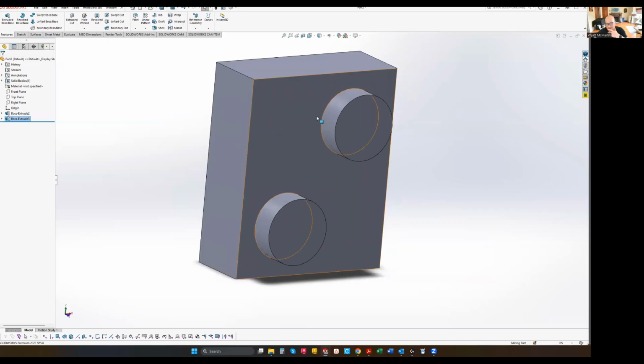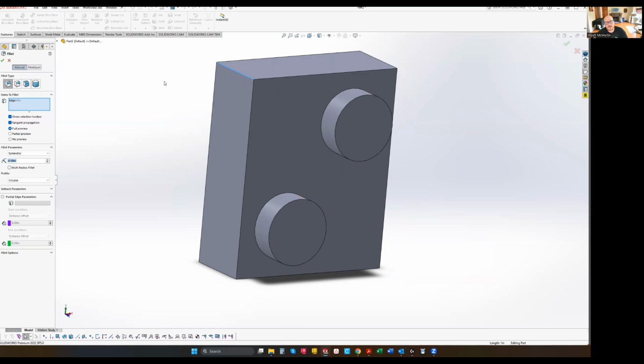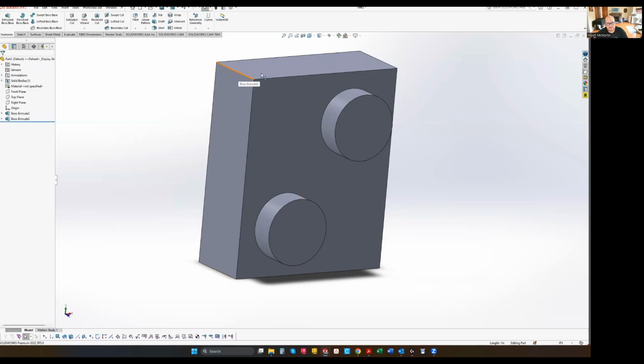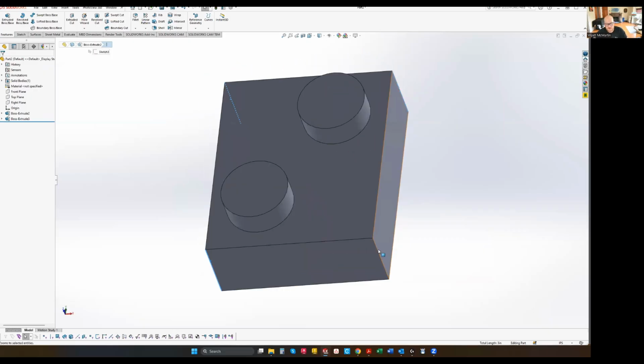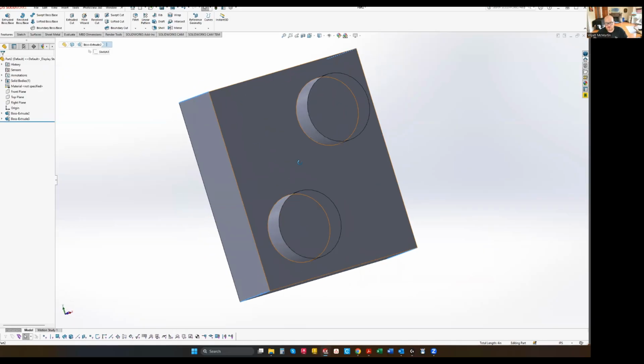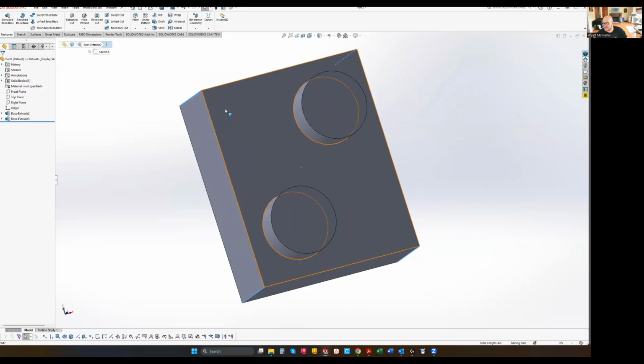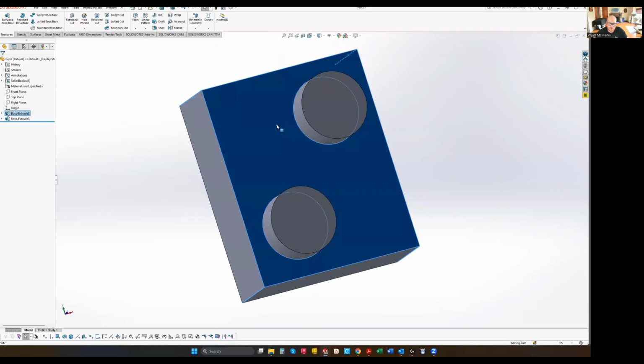So first thing, you can create these fillets one at a time. I think it's definitely better drafting practice, and it also is just nicer for somebody else who might come into your model later. If you select all 4 of these edges, just hold Control and click, and you can let go of Control, move the middle mouse wheel, hold Control again and click, and it won't deselect things. So select all 4 of those edges or corners, I guess, and then this face.